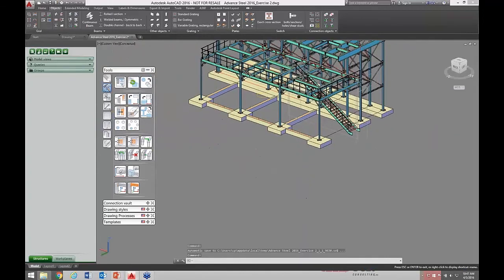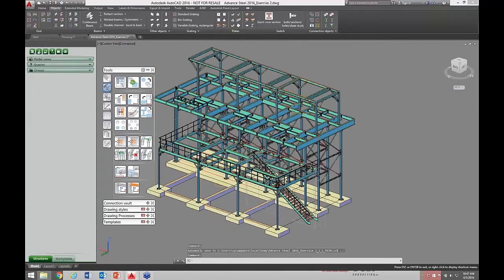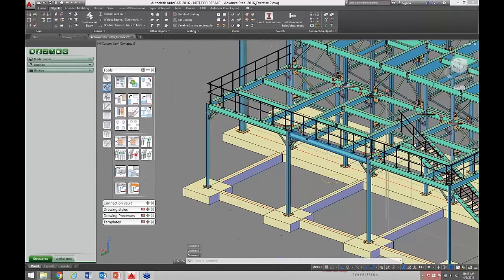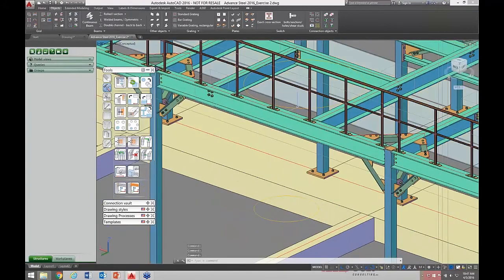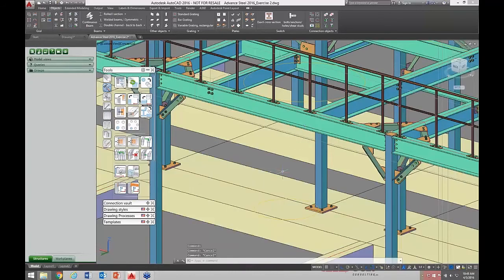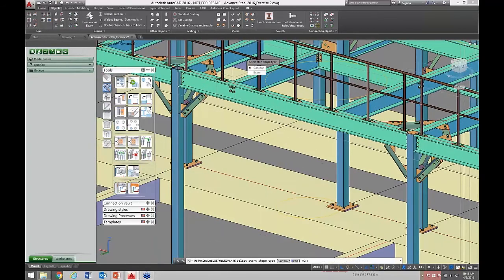All right, let's look at some plate capacity here. I have a couple of references within the model, and if you can see clearly enough, I've got a couple of circular pieces in here, a couple of AutoCAD circles at differing elevations. You just select both of those and orbit around, you can see that. We're going to create a conical plate transition here, just a conical transition by picking these two members. I tell it I'm picking a contour. I could pick a beam reference if I had that and it was applicable.